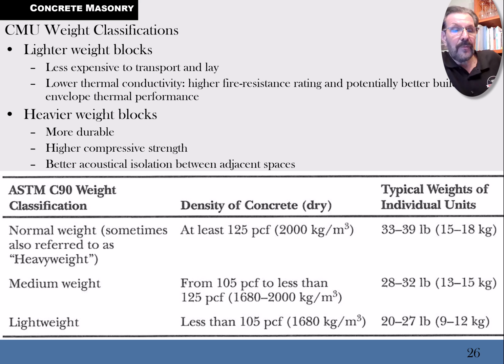So what's the difference? It has to do with the aggregates, because the concrete that they make these blocks out of, they use pea gravel for the largest aggregate size probably in the concrete, I would say. Yeah, maybe up to ½ inch. Pea gravel is considered kind of 3/8 of an inch or ½ inch, somewhere in that area for the size of the rock. So bigger than sand particles.